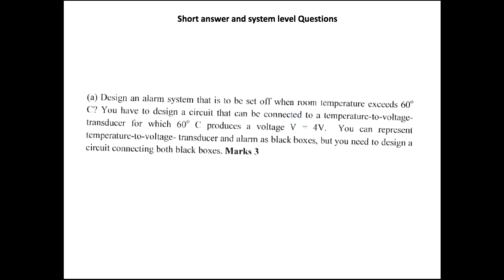So you can do it in different ways, whichever way you like. So how can we do it? Yeah, we can use a comparator, put a 4 volt threshold and then connect to an alarm. So that's a simple way.